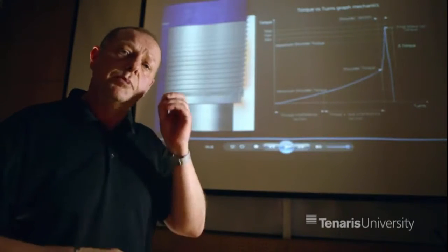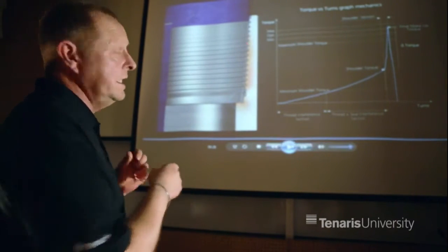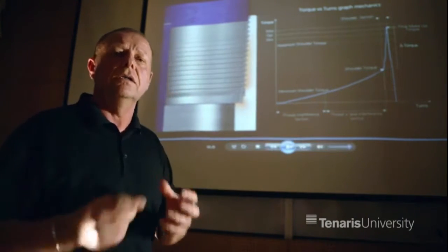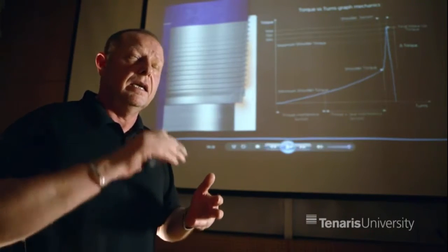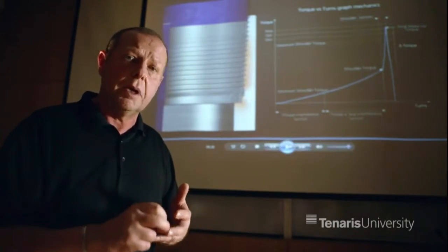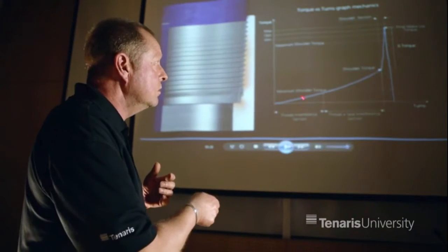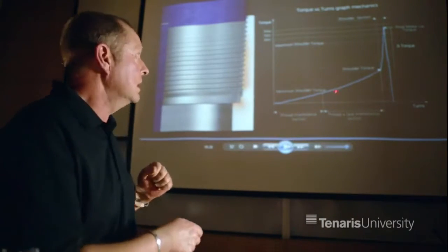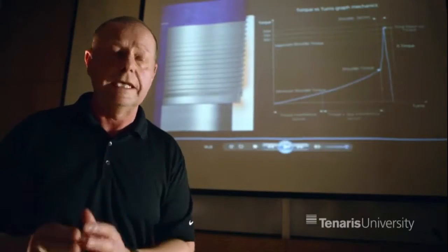Now, the experienced specialist can translate all this into what's happening in here, and that's why the person interpreting the graphs must understand the connection and must understand the design and the connection mechanics and how that connection in each individual part interacts with the corresponding part in the box connection. So at any given point within this build slope and within this delta torque build, the individual knows exactly where this connection is in its assembly process.